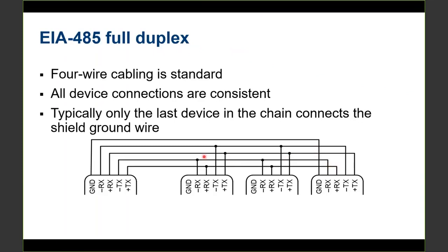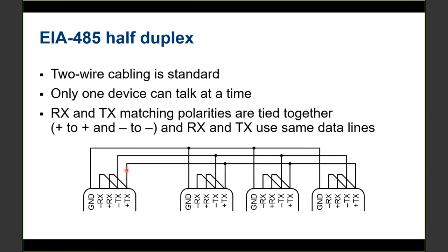So I hope that makes sense. You're measuring a TX plus and a TX minus, I'm sorry, not a TX plus to ground or a TX minus to ground. It's TX plus, and you're taking the difference between these 2 voltages. So it's an important concept to understand.